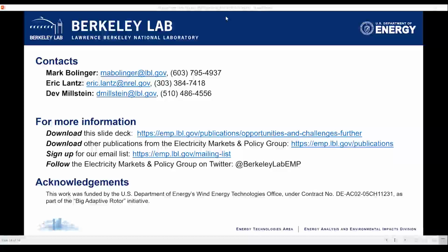Yeah, so that specific figure just looked at the number of hours a turbine operated at rated capacity. That specific effect is from shifting the point where a turbine operates at rated capacity down the wind speed curve. So maybe the low specific power curve operates at 100% of its rated capacity starting at 8 meters per second instead of 12 meters per second, or some number like that.